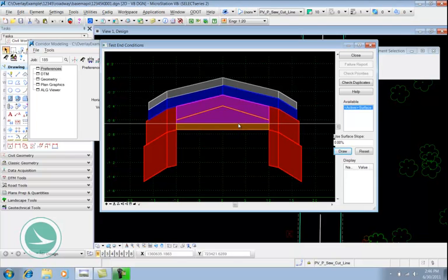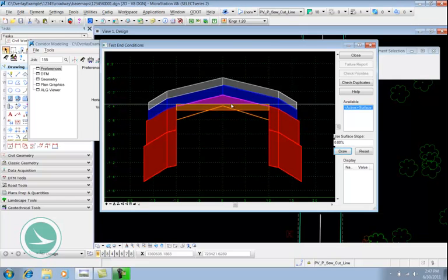And then in orange I've got my stripping component, and the top of that's going to follow the ground and then go an inch below that. And the purple one actually overlaps that because I had set it to go an inch below the surface. So the orange one will represent that pavement planing, and then the purple one will actually be defined to fill that back in as far as the quantity values for those.